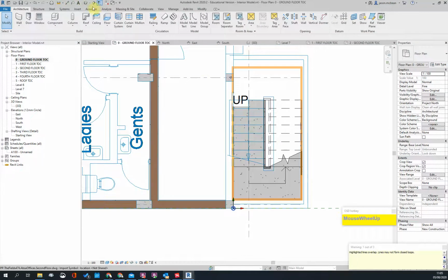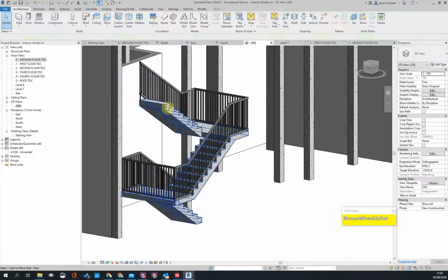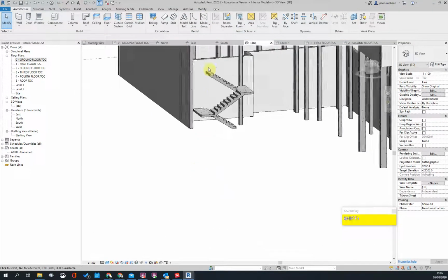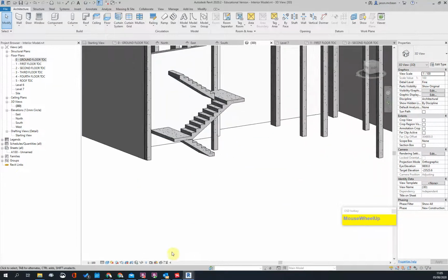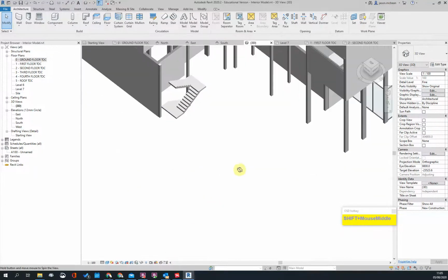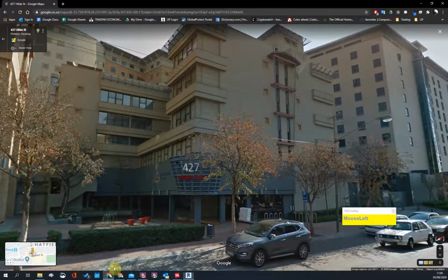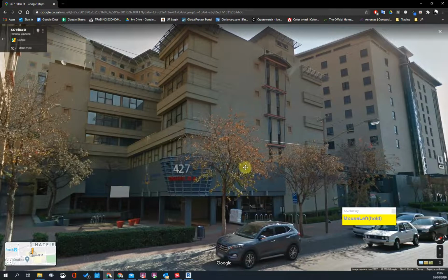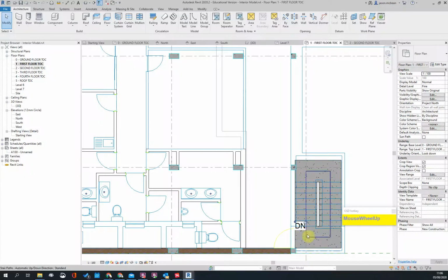I'm not worried about the nitty-gritty detail for now. And there's a wall that's going to go around it. I'm going to delete the hand railings. Okay, so in essence, I've got a step. I've stopped it 1 stair short because I'm going to use the floor slab to correct that for me. But in essence, I think if we looked at the floor plans, that step does go around. You see it goes around and then probably goes back up to that last level. Okay, but that's information that we can fine tune. We'll probably have to go and have a look at the floor plans to kind of make that work a bit better. But first floor level, yeah, that kind of works, and the stairs stops and you come out here.